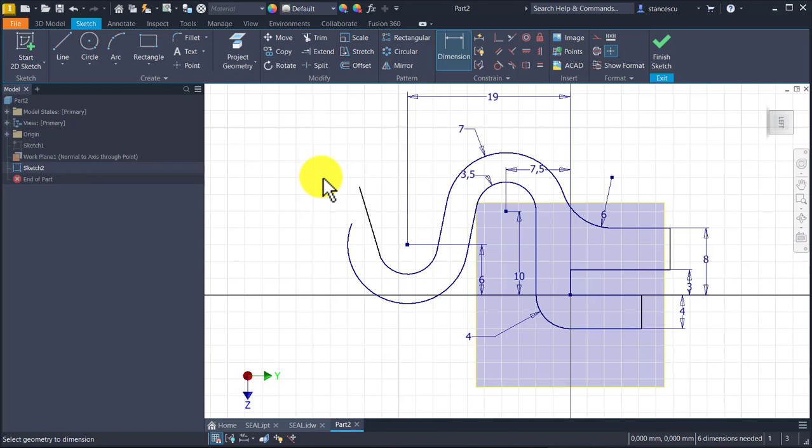Now I place that circles to cut them and to become arcs. This is with the radius. You see here is the radius 0.7. The other one is 1 millimeter radius, and the other one is equal to the last. I place equal.